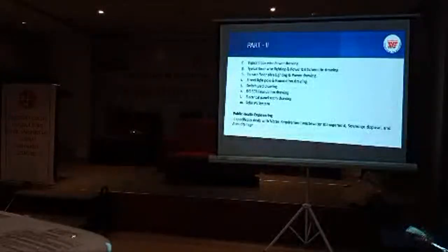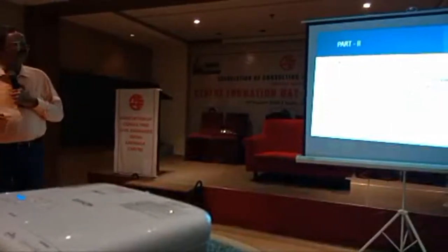This is what I insist in all my projects. Every consultant has to give the schedule of drawings so that the engineer on site knows what drawing to expect, what drawing he has to wait for. List of drawings, and then all disciplines we have given, what are the minimum drawings to be given for consultant, gas supply, MEP coordination, here